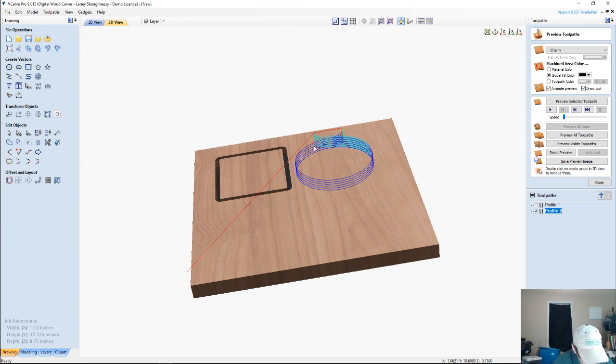In plywood, a lot of times when we do joints, dado joints with our router, sometimes we'll actually score the outlines of that dado to break that surface, so when we cut out that dado, when we're handheld routing, it's going to reduce the chip out. We take a box knife or a scoring knife, and that helps reduce the chip out when we're running our router back and forth.